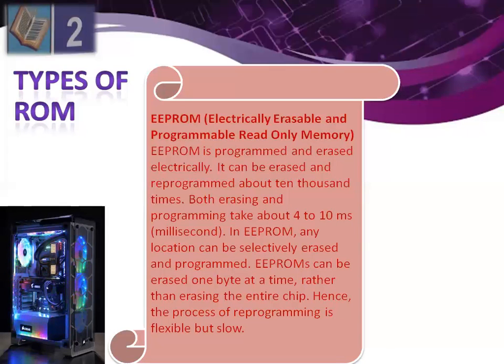So EEPROM, which stands for electrically erasable PROM, is also being used for ROM applications. The EEPROM can be altered while being used in a logic board by using special power circuits and a write pulse generator. The EEPROM can work like a read-write semiconductor memory while retaining the non-volatile nature of ROMs and PROMs. This type of ROM works in a similar way to flash memory. It is used to store a computer system's BIOS and can be updated without removing it from the circuit board.